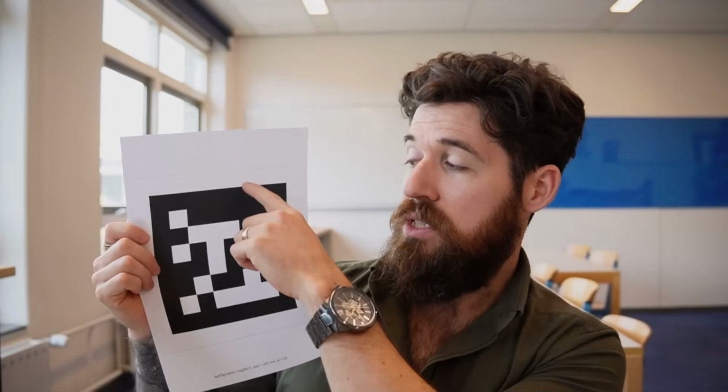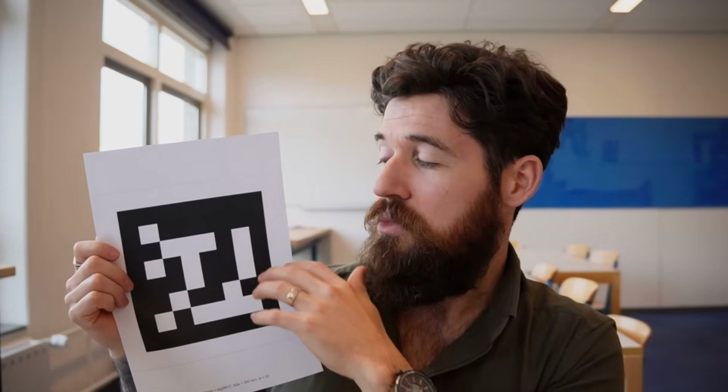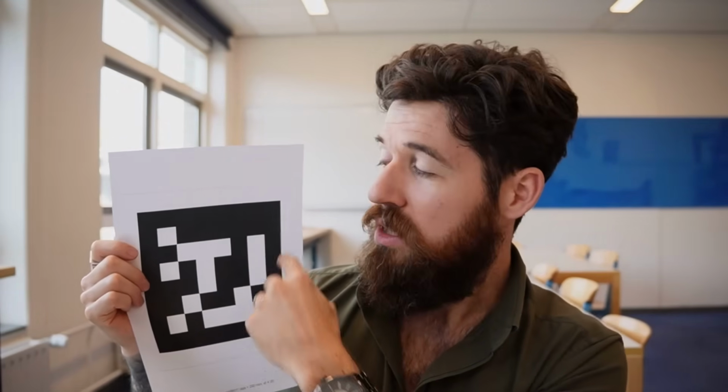So it allows us to have a common reference point for robotics to look at these tags and say, okay, I know I'm looking at ID 20. And because they all have fixed sizes, this image here is 200 millimeters by 200 millimeters across. Because you know the fixed size of this and you know the fixed size in your camera, you can use some inverse square laws to do a calculation to say, okay, if the image is this big on my screen, then we know how far away we must be.